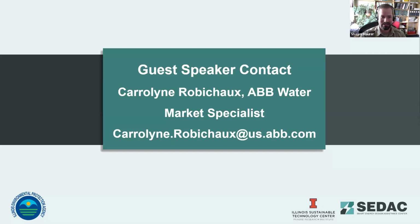So Wheaton's the only one I'm aware of that I know has used feed forward. I'm not sure if they're still using it or if they've adapted to a new process, because that was a number of years ago, 5, 6 or more years ago, that we ran across that at their facility. The grand majority of plants I see are doing some version of feedback control, or a cascade control with ammonia into a DO controller, where that ammonia is sending a change in the DO set points, and then the DO controller is making sure the process is controlled based on a feedback loop.